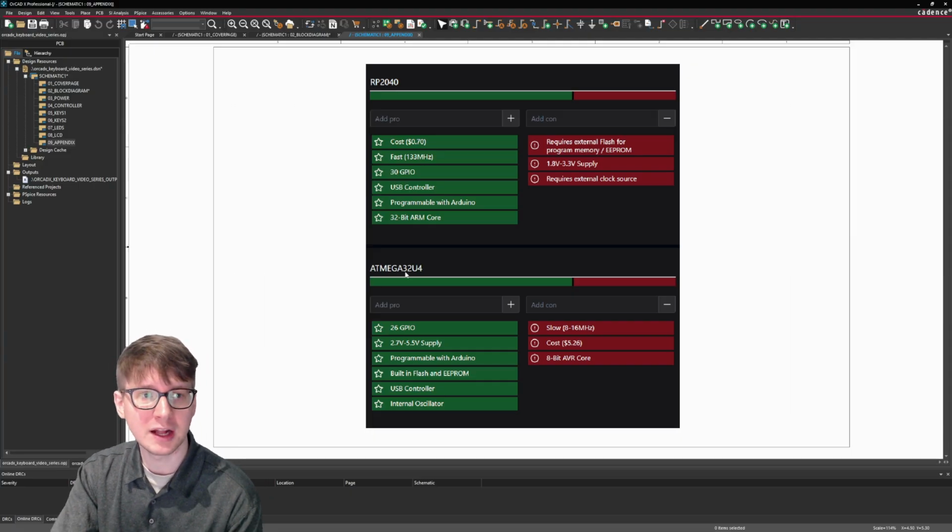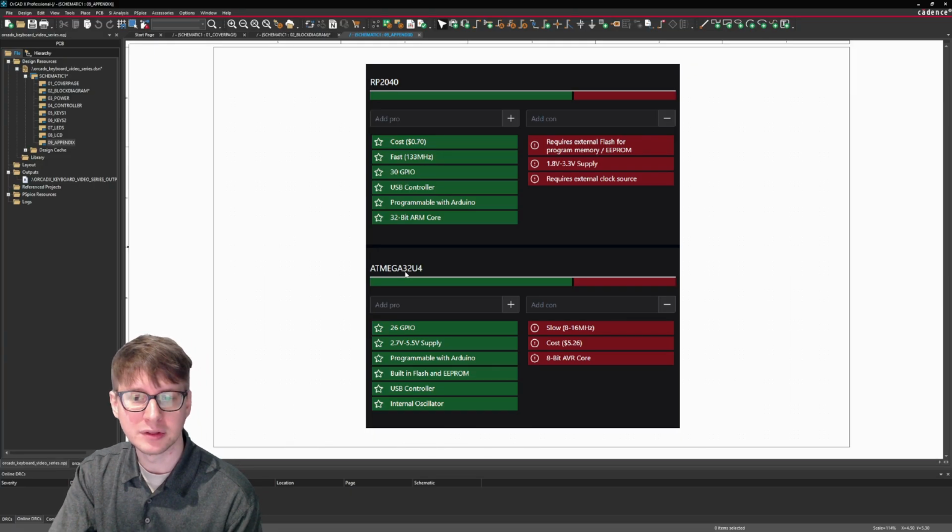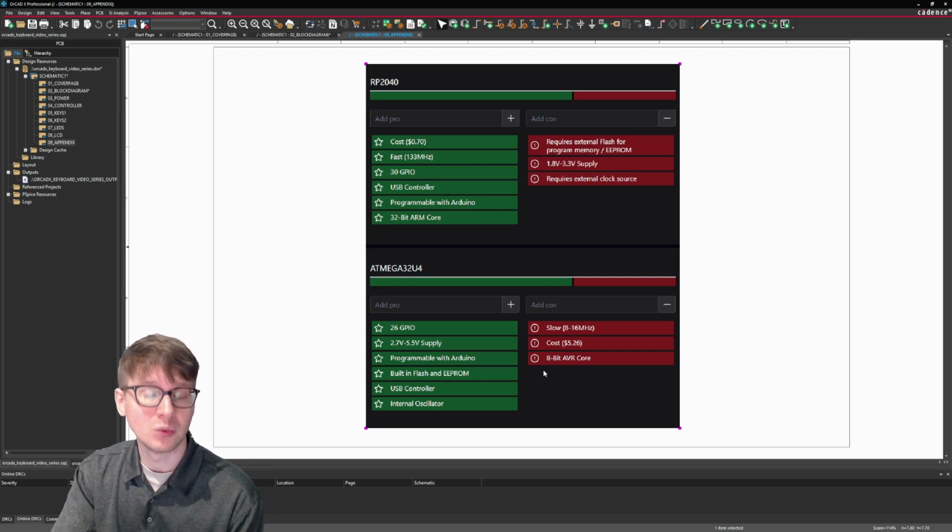That also means that when we're talking about the digital signals that are going to, for example, our LEDs, the IO expander, the LCD, those can all run at 5 volt logic rather than 3.3 volt logic. And then if something like, for example, the LED modules require 5 volt logic in order to function, then we won't need a logic level shifter.